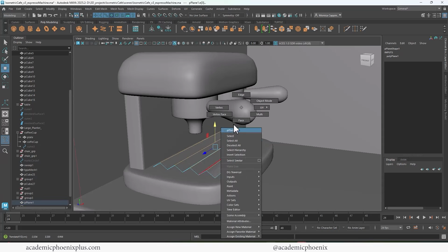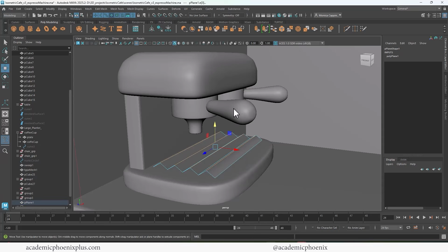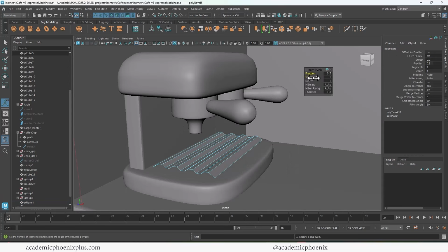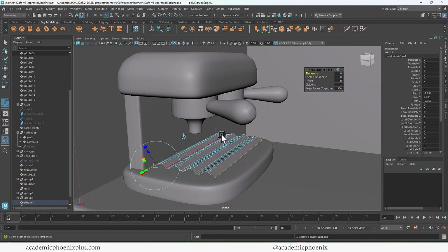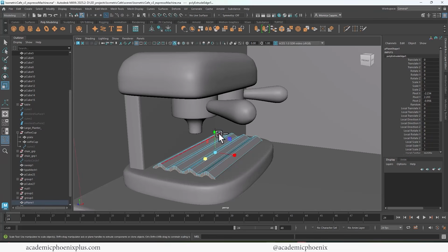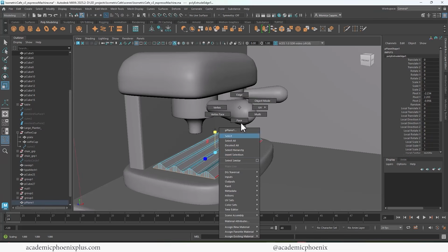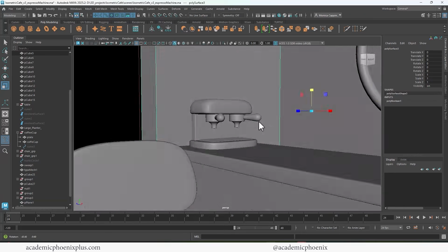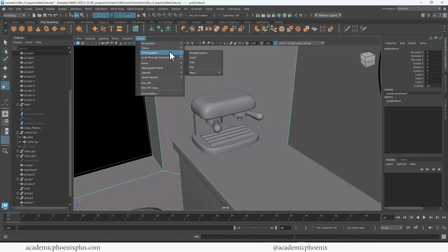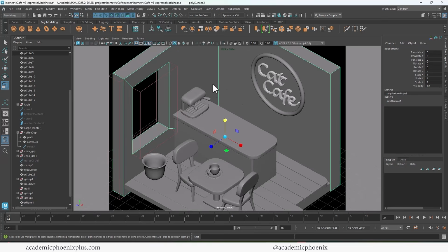And then I'm going to go to edges again. I'm still there. Select all of this and do a Control B, which will give us fractions and segments. And then I'm going to double click on this, Control E, which is extrude, press W to go down and then scale it flat. And then I have this piece. Ta-da! Orthographic render view. There you go. Let's take a render.